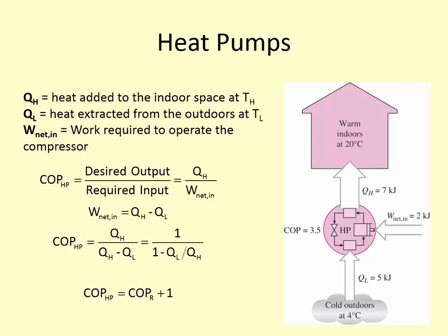Well, if you think about the temperature difference between your house and the outside in the wintertime versus in the summertime, that's where the difficulty lies. Even though it's 90 degrees outside, maybe that's only a 20-degree temperature difference between your thermostat and the outside, so there's less heat that needs to be removed from the inside. But in the winter, if it's 0 degrees outside and you're trying to maintain 70 degrees, that's a 70-degree temperature difference that you're trying to overcome.